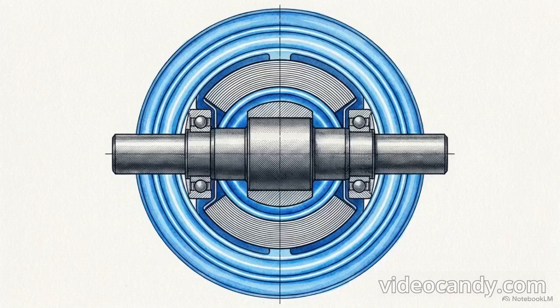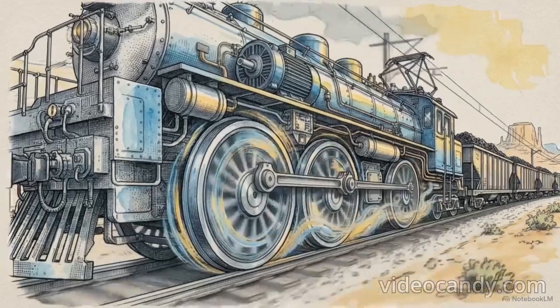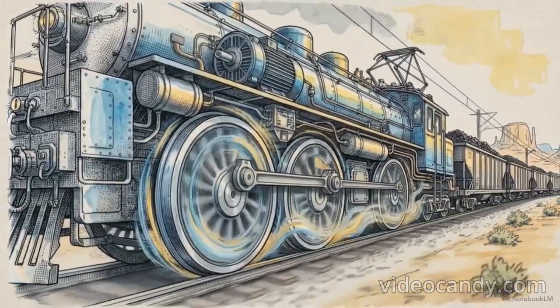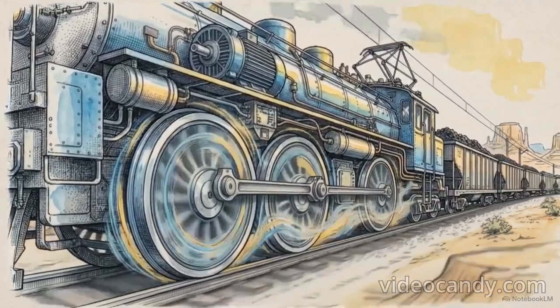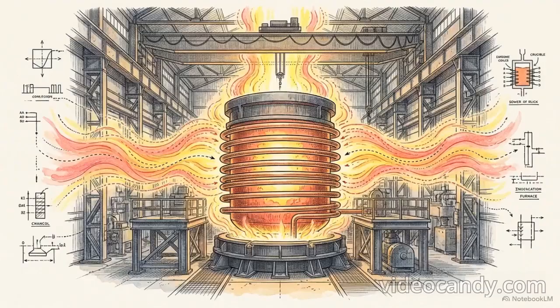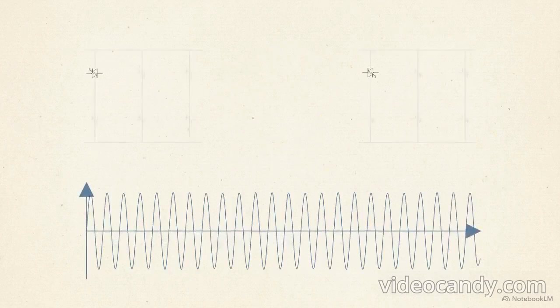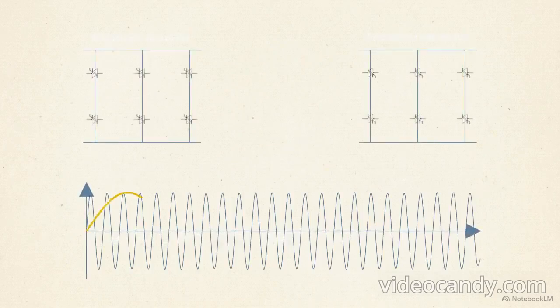Its digital signal processor rapidly adjusts the internal firing angles of the thyristor bridges, delaying or advancing the pulses. This dynamic shifting alters the RMS voltage output at the exact same moment it synthesizes the new target frequency. Because it controls both variables simultaneously, direct cycloconversion maintains constant torque across variable speeds, ensuring flawless heavy-duty control over megawatt drives. Seeing an industrial electric train or a massive mining drill accelerating smoothly under thousands of tons of load means you're watching these principles in action.